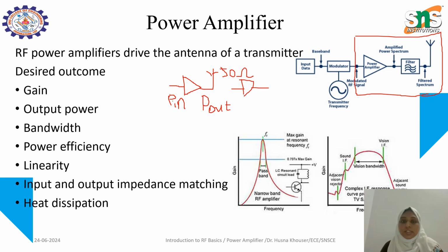Let us consider we have the optimum amount of impedance, based on what the antenna requires. For example, if it is 50 ohms, the filter will change this output, optimize the impedance, and match it with the antenna, so that we are able to transmit the signal.